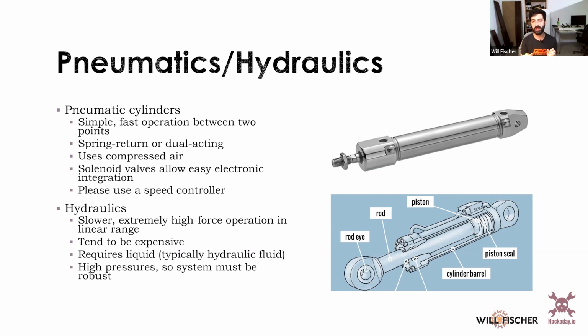And I would absolutely, for hobbyist purposes, use a speed controller. And that's a little needle valve that you put on the inlet, and that allows you to dial the speed down, which is important. If you open those all the way up, pneumatic cylinders move scary fast and you can hurt yourself.